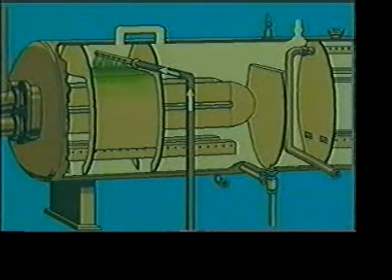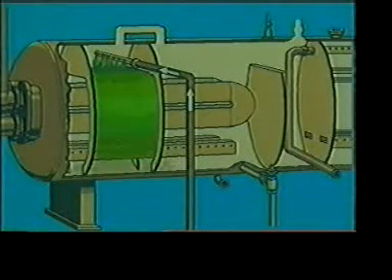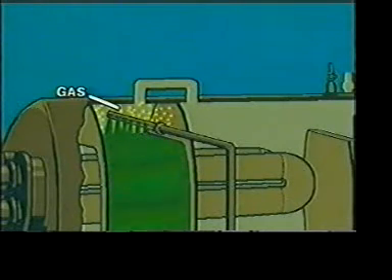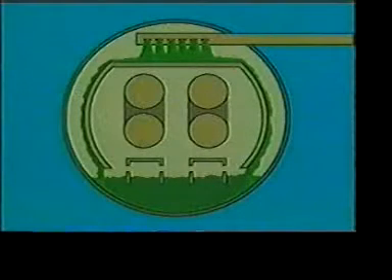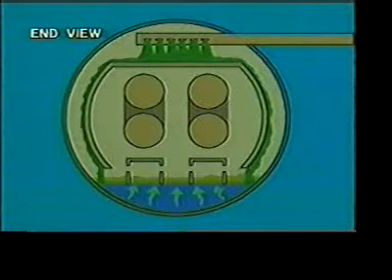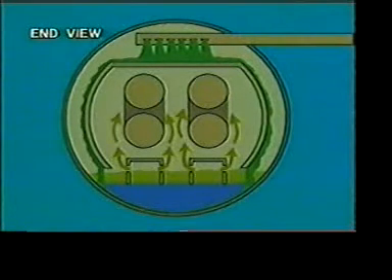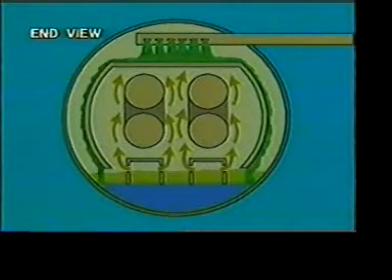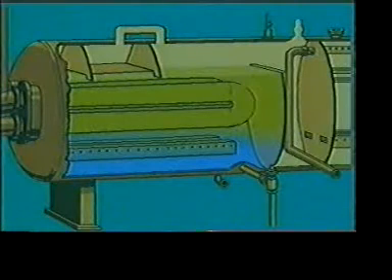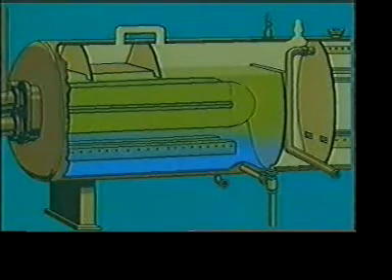As the emulsion enters the inlet section, it splashes over the downcomer and flows downward to the bottom of the vessel. Free gas is released as the emulsion strikes the downcomer and rises to the top of the inlet section. Most of the free water in the emulsion quickly settles out, and the remaining lighter liquids move upward through the water, which serves as a heated wash. As the emulsion continues to rise, it flows through a spreader, which distributes the emulsion along the length of the fire tubes. As the emulsion moves upward across the fire tubes, several things happen.